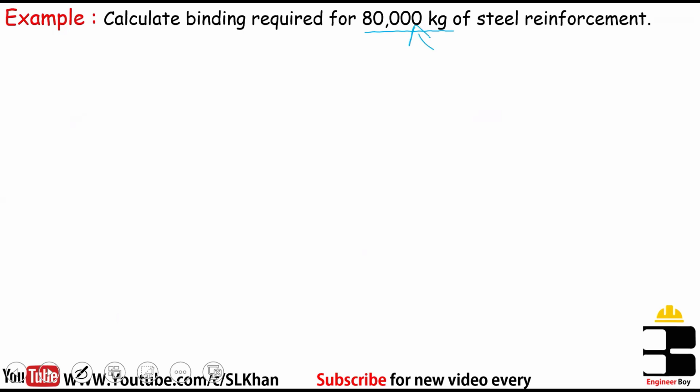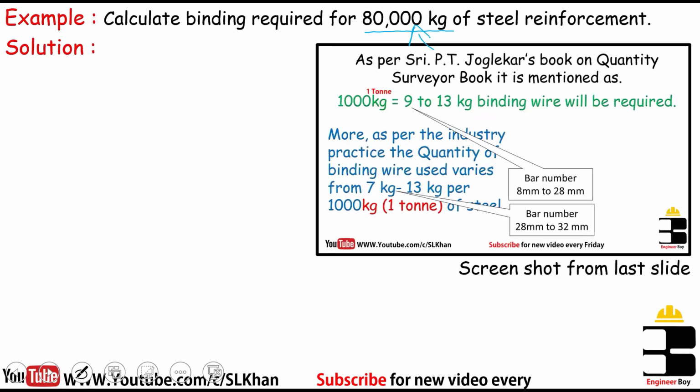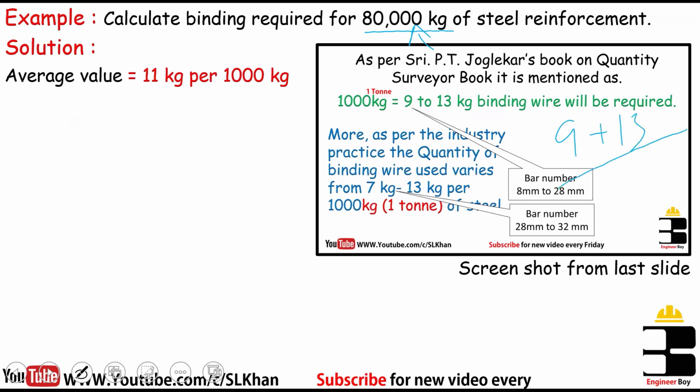You have to remember that thumb rule in order to calculate the binding wire for the same project. And that thumb rule, you can see it in this screenshot. Now, the average value is 11 kg per 1000 kg of work, because if you take the average of 9 and 13, that is 11. It means 11 kgs per 1000 kg.